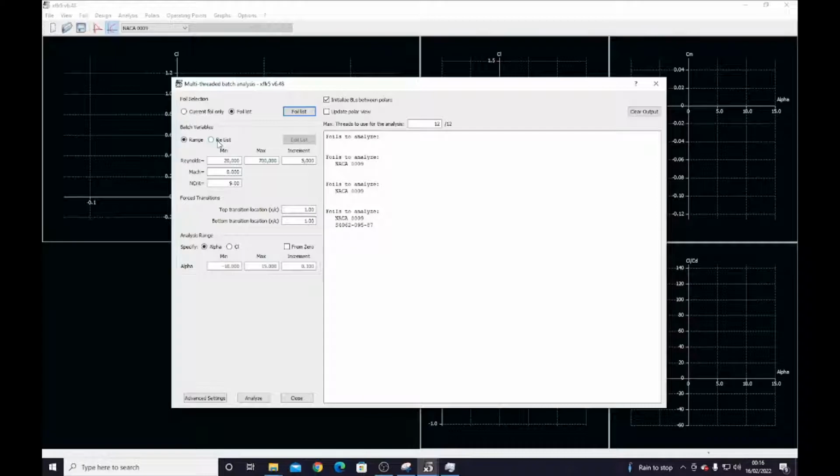Our aircraft will fly in regimes somewhere in the hundreds of thousands of Reynolds, between 100 and 600,000 Reynolds. Turbulent transition occurs at about 400,000 Reynolds, so we want to make sure that we cover that range as well. Because there are stall cases and edge cases, we'll be making sure that the range is between 20 and 700,000 Reynolds, which, in fact, I'm going to make 800,000.